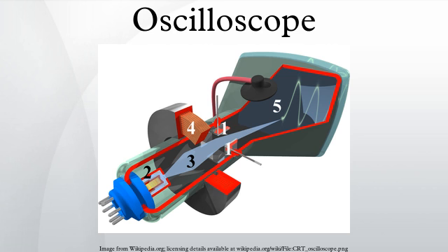On old and lower-cost CRT oscilloscopes, the graticule is a sheet of plastic, often with light diffusing markings and concealed lamps at the edge of the graticule. The lamps had a brightness control. Higher-cost instruments have the graticule marked on the inside face of the CRT, to eliminate parallax errors. Better ones also had adjustable edge illumination with diffusing markings.